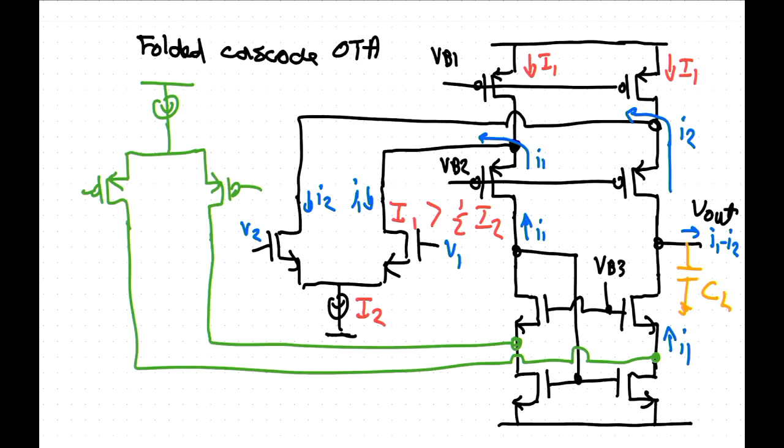That's going to raise this voltage. So if you push a current into that, the gate source voltage of this one here will actually increase to accommodate that current. Well, that means that we're going to have more current flowing into here. So it has the same effect as putting in a current here. You can put in a current here, and this still comes out like that.